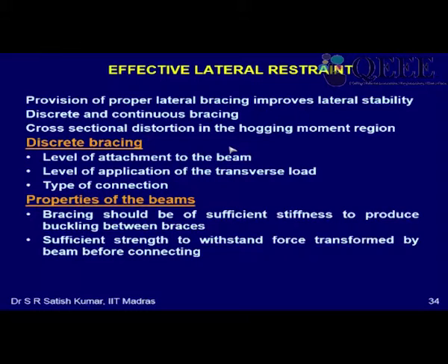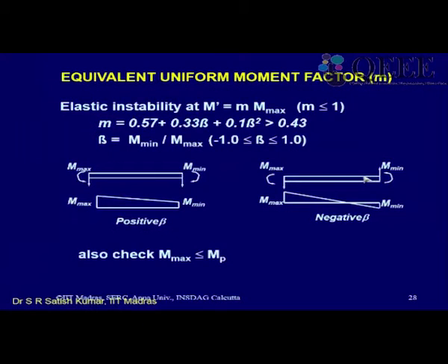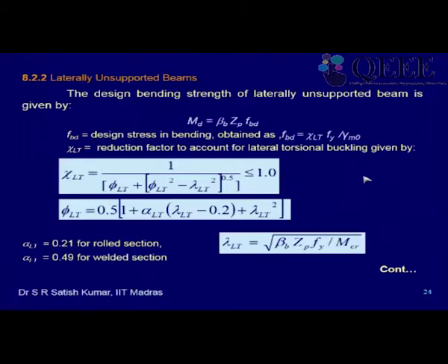So now how to give lateral support to the bottom flange? So what they do is they give something called fly bracing, where the bottom flange is connected to the purlins on both sides. So there will be a small member which connects the bottom flange of the rafter to the purlin, and that gives you the lateral bracing required. Okay, so if you want me to show, let me just go to a cross section of an I section.